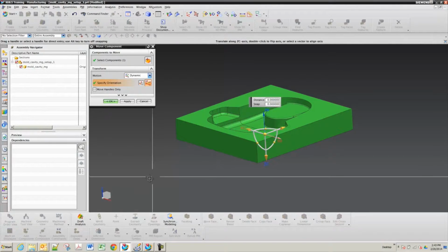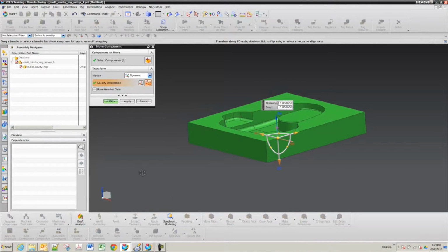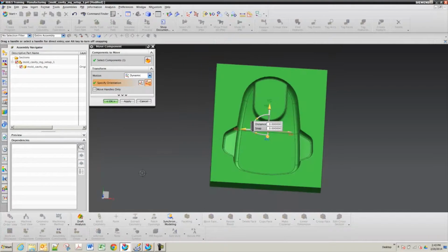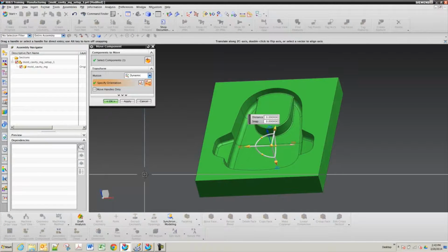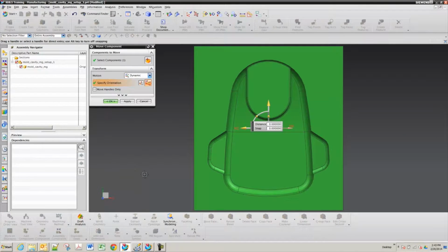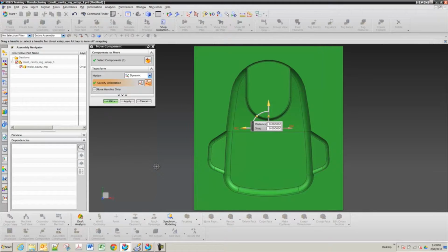You can see if you look at your view, our view Z is pointing up, it was opposite. So now by doing that, when we hit the top view, we're looking at the top of the part. If you want to rotate it or anything, you can do that too. You guys want it sideways or do you care? Is it okay like this, or do you want to rotate 90? Okay. So you click on the sphere between the X and Y, and you can enter a value. If you enter 90 and hit enter, it'll move it.